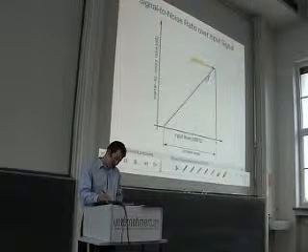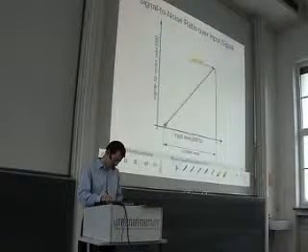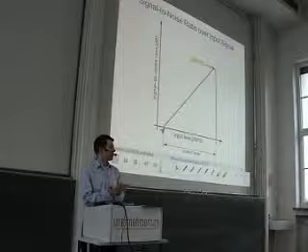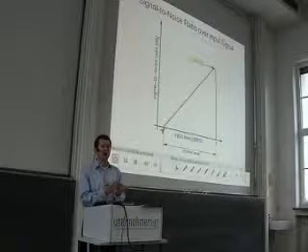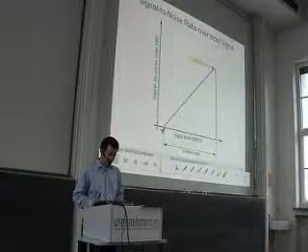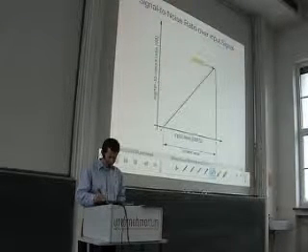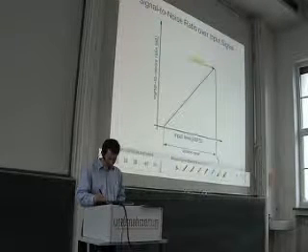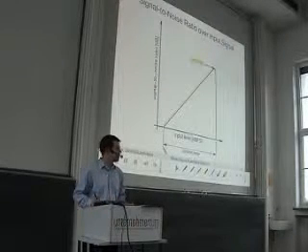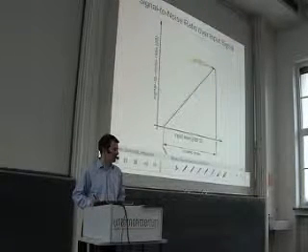If you reduce the amplitude, then you go down with your signal to noise ratio and down and down, and somewhere the value reaches 0, which means that the signal power corresponds to your noise power. And then it makes no sense to reduce the signal further, because then you measure nothing but noise. The value of the maximum allowable input that can be used for this device, and the difference to the value where we have the 0 dB, this is what people call the dynamic range of the ADC.